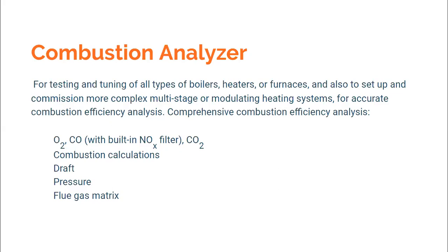If the air supplied is more, you get more oxygen. If it is less, you get less oxygen. How to use that data in the calculations, we'll see later. But an oxygen measurement in the flue gases is an important parameter which gives you an idea about the phenomenon of combustion, whether the combustion is with excess air or whether it is with an incomplete air-to-fuel ratio. Similarly, the combustion analyzer, with its inbuilt probes and sensors, will tell you how much carbon monoxide and how much carbon dioxide there is.